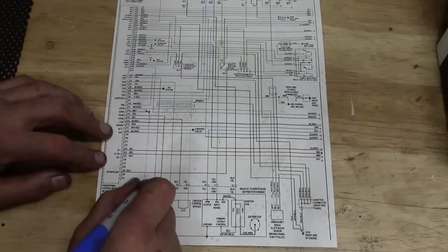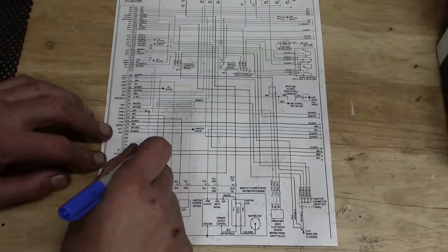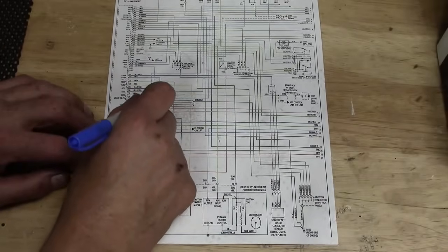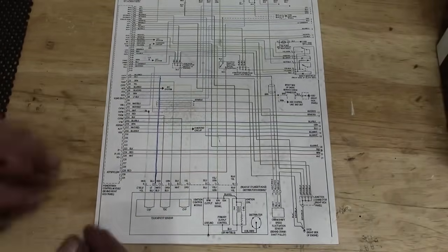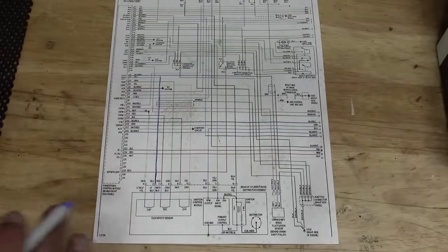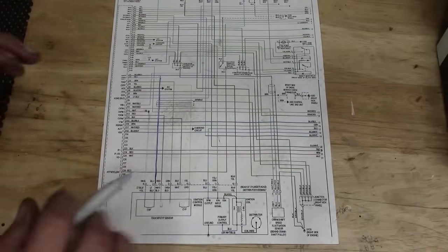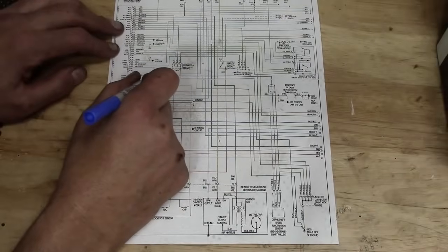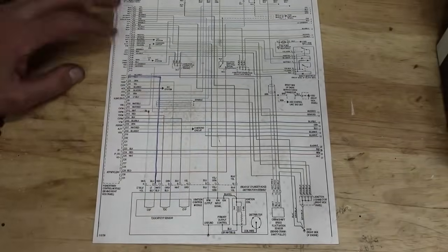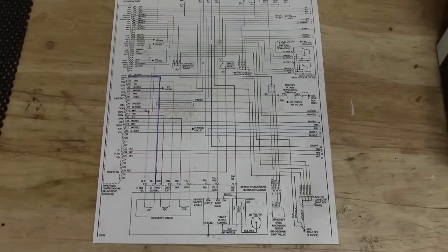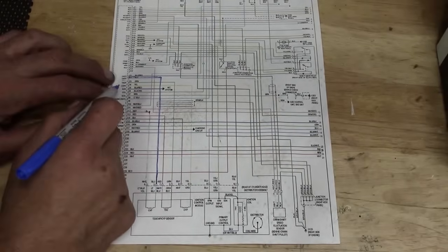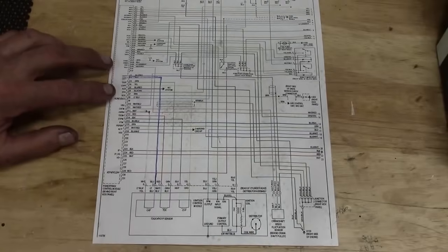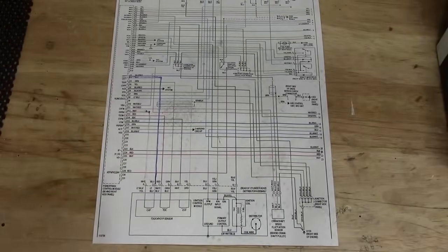But I'm just interested in this side. And actually, I'm probably going to draw this over again on my dry erase board anyway. I often do that on these more complicated systems because that way I can draw just the system I am interested in. Anyway, that comes across here and it goes to CKPP. I'm assuming CKPP is crankshaft position sensor positive, and maybe that's negative. I don't know, but whatever the case is, I know how it's going to work. I just don't understand the labeling there.